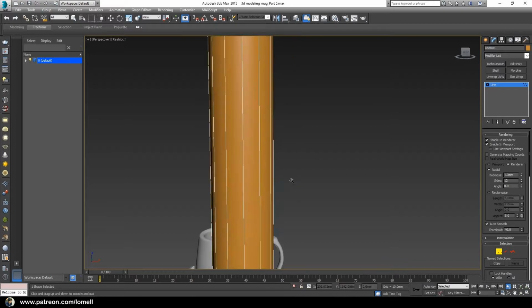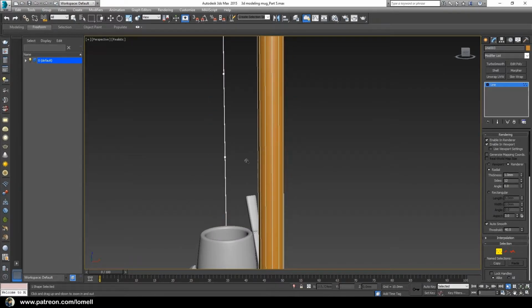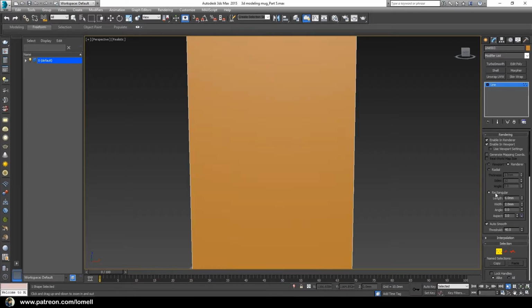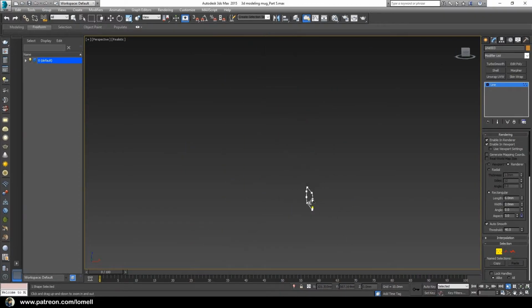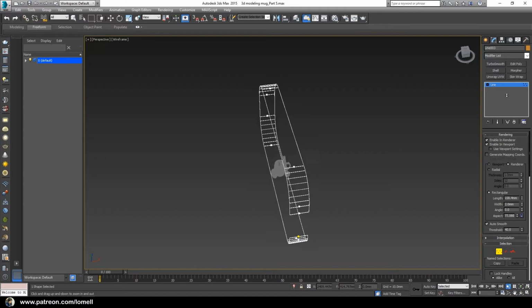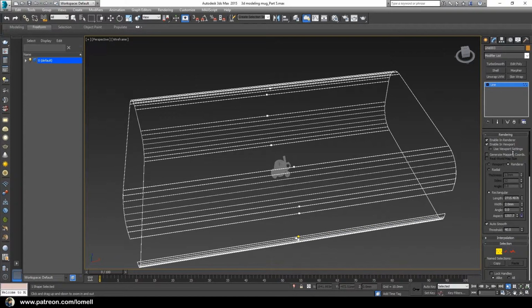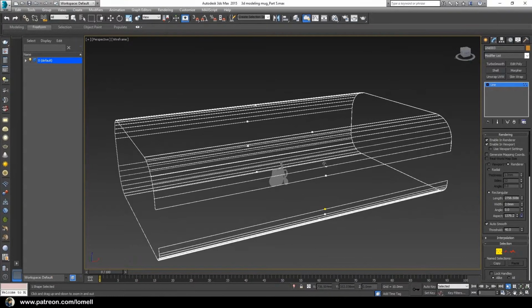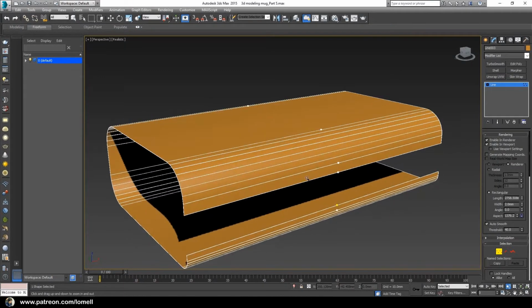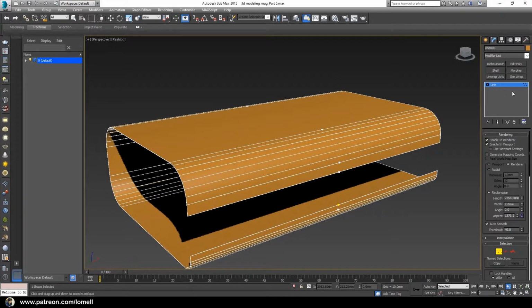Okay, so this is currently in a radial shape, and I want to change it into a rectangular shape. Okay, check this one and zoom out. Press F3 so that we can see through our object, and let's expand the length value by dragging these adjustment arrows up. Okay, drag this up, and that should be enough. And now press F3, exit our editing here by clicking this layer.